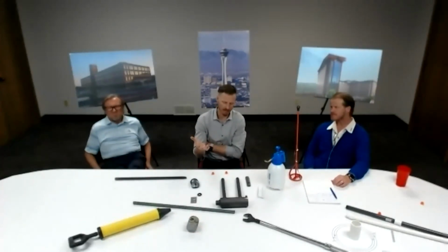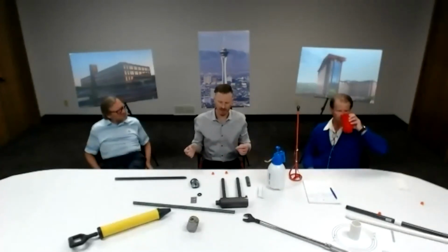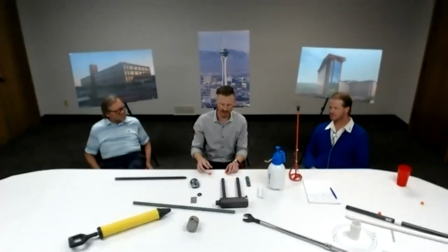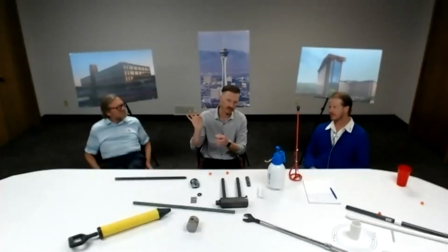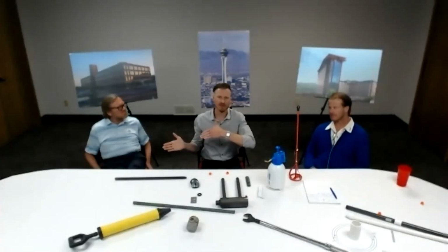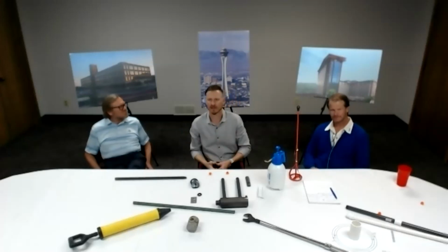On one of our jobs, they didn't really worry too much about where the tops were. They just finished over top of it, and then they thought if they could find one little concrete cap, they could find the others and chip them out a little bit. So back to that question about a nicer finish, your finisher could finish over top of the caps and then just knock some of that concrete out later and re-pour, and it could be a much cleaner way of doing it.